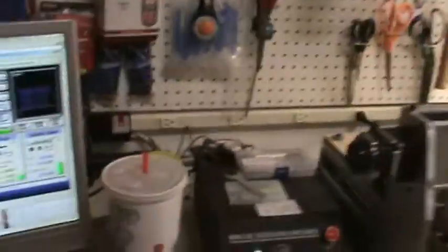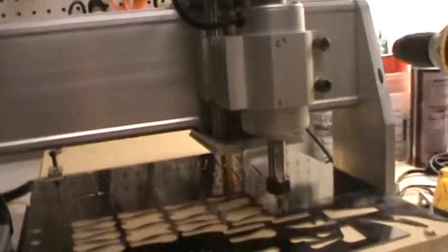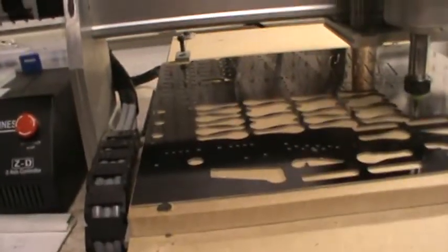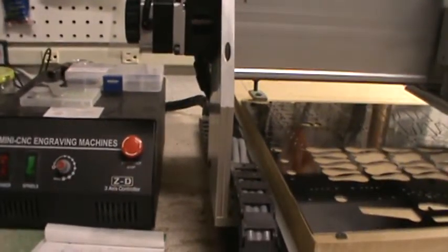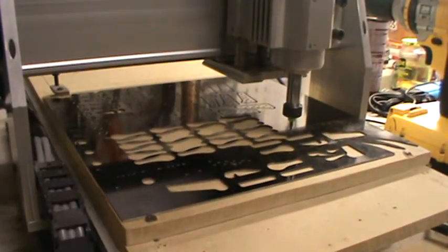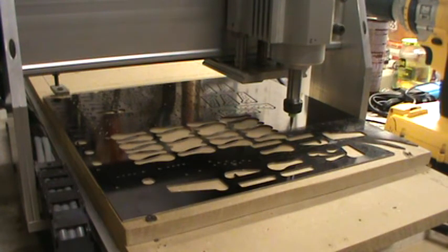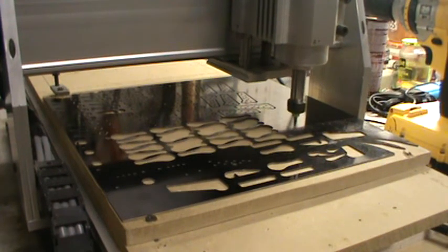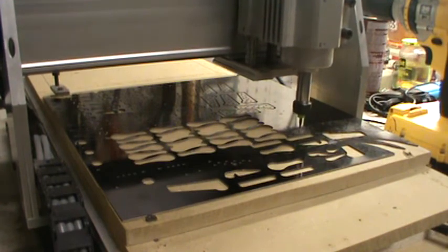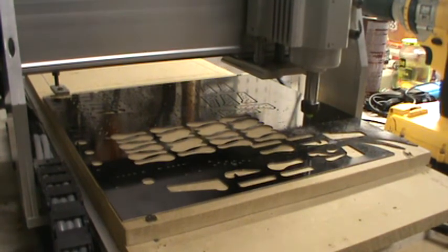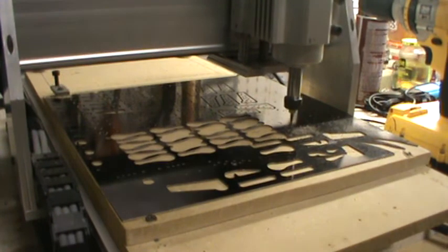So let me get the camera back up on the tripod and get it level so y'all aren't all crooked on me. And then over here on Mach 3, I'm going to turn the spindle on, raise the bit up just a little bit, and then hit cycle start on Mach 3. So the machine will start doing its work. And turn on the shop vac so I don't get the place all dusty.